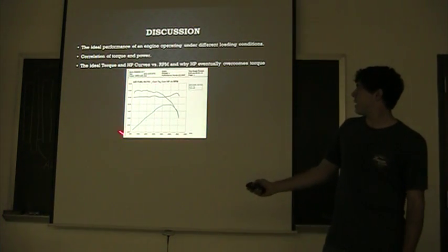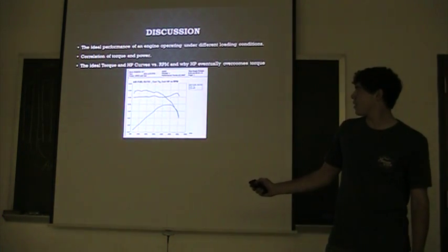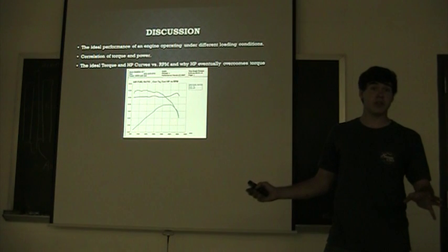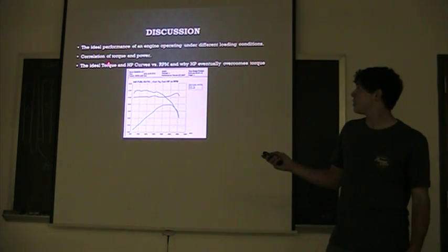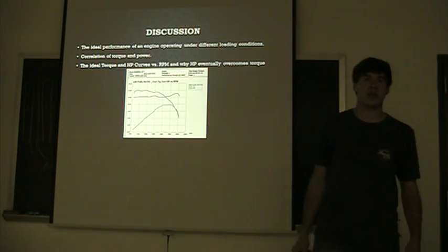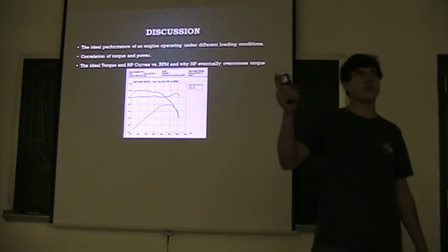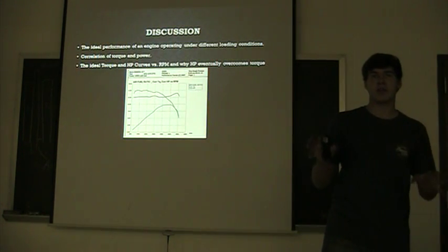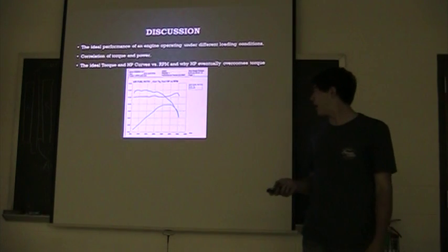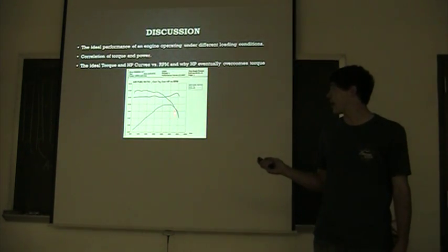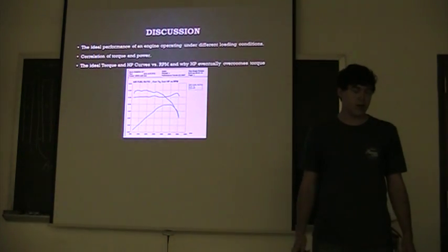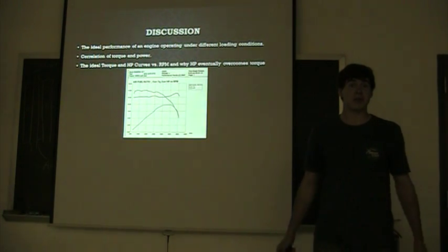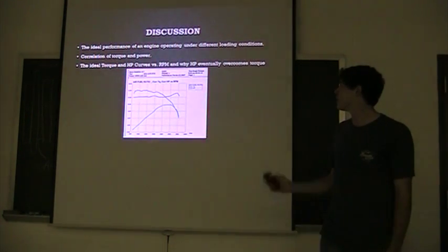And here's just what your basic horsepower and torque curve should look like. So here we have torque up top, and horsepower comes over and crosses it. Should cross it at 5250. There's an equation to use when we talk about power and torque. It's horsepower equals torque times RPM over 5250, give or take. And that's one way to know if your dyno's reading accurately. If they don't cross right about there, then you can't really believe your numbers. You messed something up, so recheck.